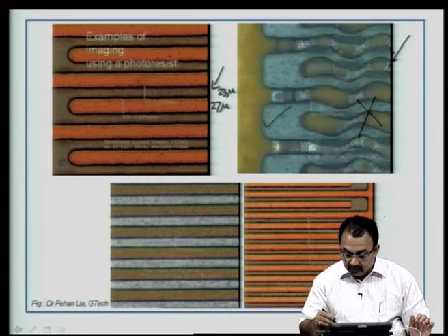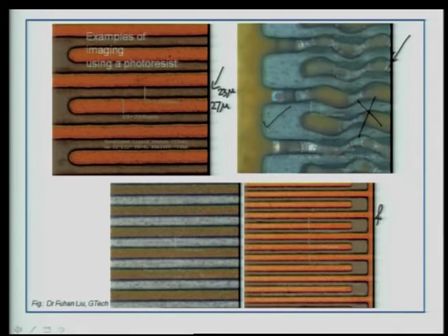And here again below we are seeing very fine line structures being done. For example, this is a 40 micron track and the gap is around 38 microns. So, very fine lines sometimes are required in the PCB industry.